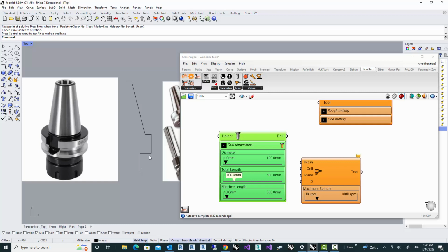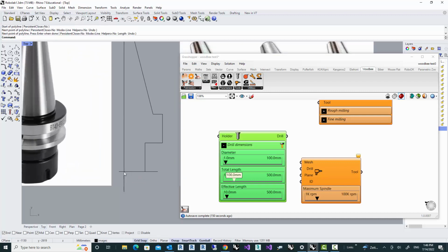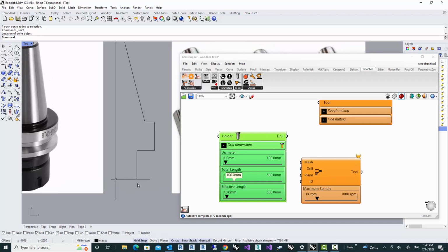And now we have to really precisely calculate these coordinates with respect to, well, I assume this would be my axis of revolution, and this would be my 0 point over here. Just put a point in the intersection. Okay, so I consider that as an origin, and then I start placing coordinates in x and y direction, and the x will be the radius of that profile in that particular height, and the y would be the height of that point.